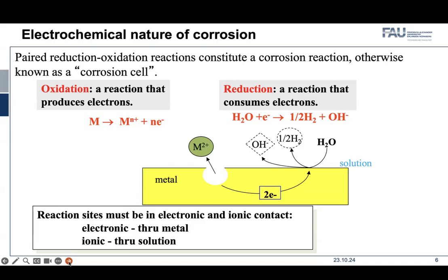At some point, there is also oxygen dissolved in the electrolyte. This oxygen molecule comes and picks up the electron anywhere on the surface, because you have produced some excess charge that needs to be consumed somewhere. The metal does not want to have this excess electron produced by the oxidation, so it will be consumed elsewhere. That's why I said these sources and sinks are constantly moving, and this process happens in milliseconds or microseconds. The site where the anodic reaction took place can become the cathodic pair for some other anodic reaction happening elsewhere on the surface. So this electron source and sink are continuously moving randomly.